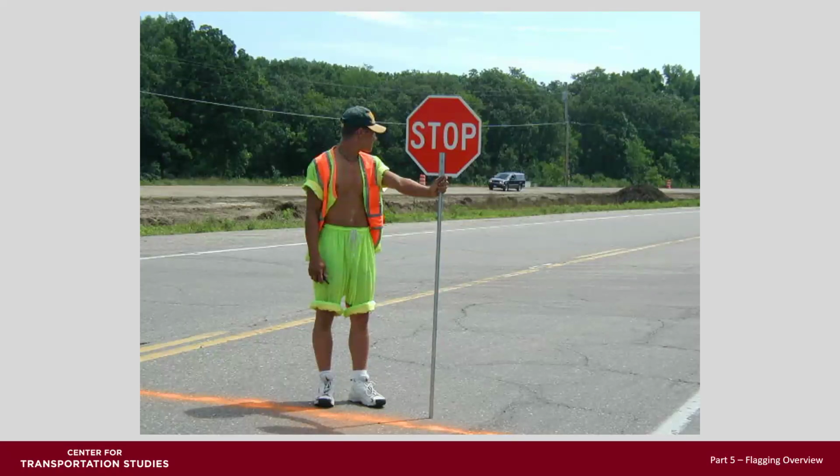Have to wear proper clothing. That clothing has to be visible from 360 degrees. You have to actually earn the respect of the driver. And again, standing in an open traffic lane with the stop sign, not facing oncoming traffic.